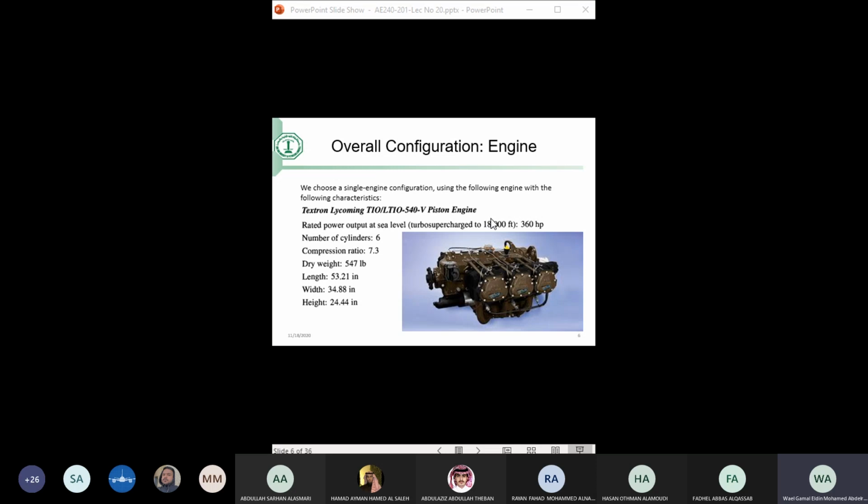But at the cruise altitude of 20,000 feet, we want to satisfy the maximum speed. Over there, in the maximum speed, the required horsepower was only 303. So if this engine is giving me 360 at 18,000 feet, then it will be able to give me 300 at 20,000 feet, because remember the curve goes down with density, so it shouldn't be a problem. I can live with that.